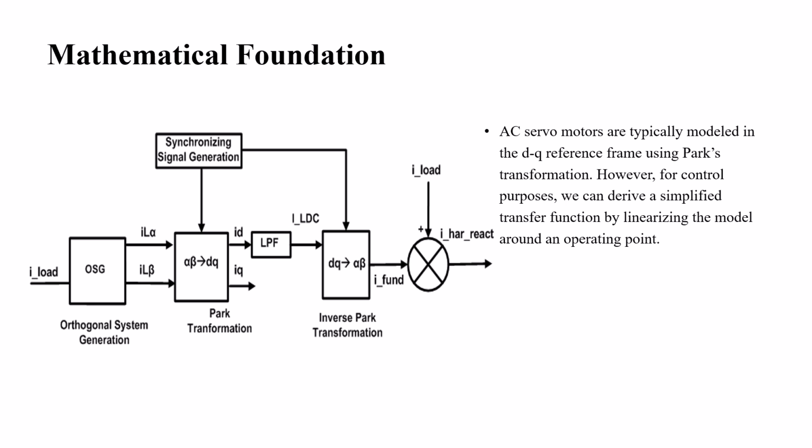Because of these, we can control whatever parameter it is: voltage, current, power, speed, or angle of position. Because we are transforming all the related parameters into one reference axis, whether it is the D axis or Q axis. How exactly this is done is with respect to the formulas derived from Park's transformation and inverse Park's transformation.